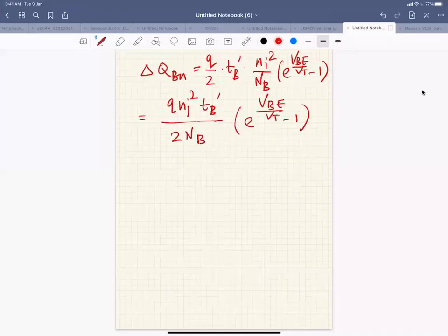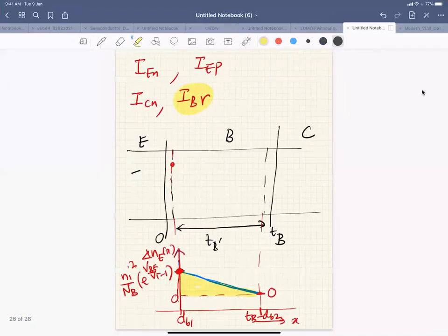So this excess charge is moving. In steady state, this delta Q is the excess carriers in the base, and the current is nothing but these excess carriers, which you are injecting, being collected at the collector, right? So you can think of this as a charge packet: I am injecting a charge packet here, and this charge packet is collected.